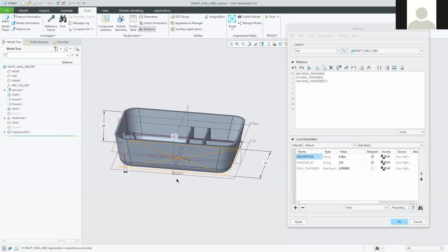So, height of the box, half the depth, right, okay. So we're going to calculate this value, which is the height of the box. So select that, and then make it equal to the depth of the box, either divided by 2 or times by 0.5. So that's how we're calculating that. D0, which is the height, is going to be equal to D1, which is the depth, divided by 2. So we can see if that's actually going to work.